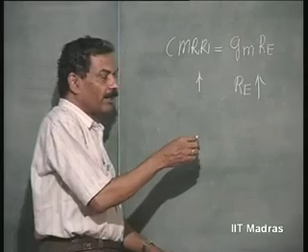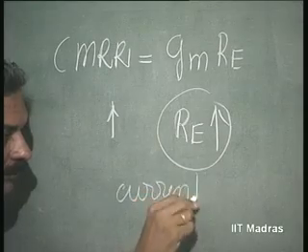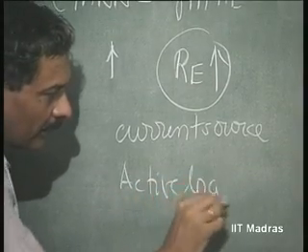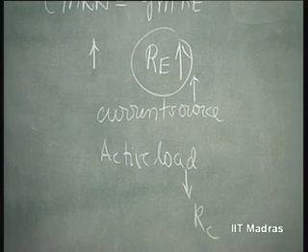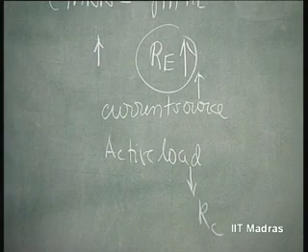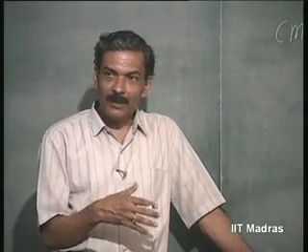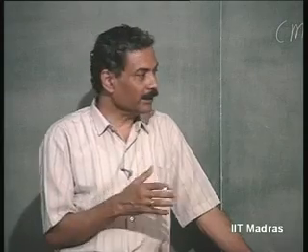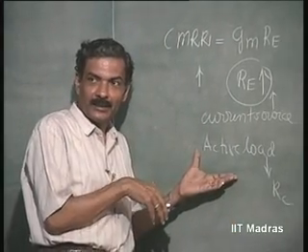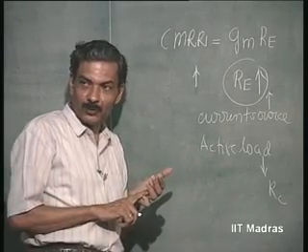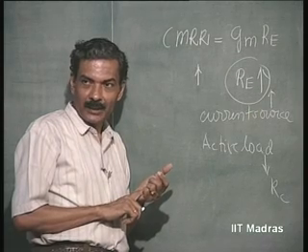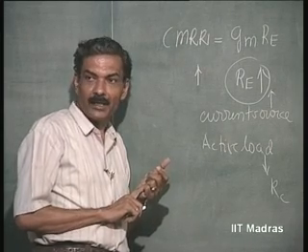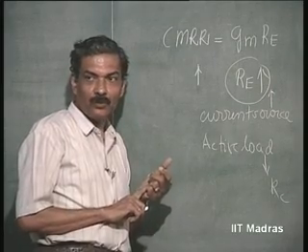So, by introducing what is called a current source in place of RE and by introducing what is known as an active load in place of RC, we can almost get rid of all the resistors required in our operational amplifier design, and the op amp will comprise only transistors, which take up minimum area compared to resistors plus transistors. Therefore, this kind of structure, which performs better and takes up lower area, is highly suited. And not only that, it solves our problem regarding common mode swing, it solves our problem regarding common mode rejection ratio, and it solves our problem regarding low valued current being reached without necessarily using high valued resistors which take up a lot of area. So, we will discuss now how to obtain these current sources.